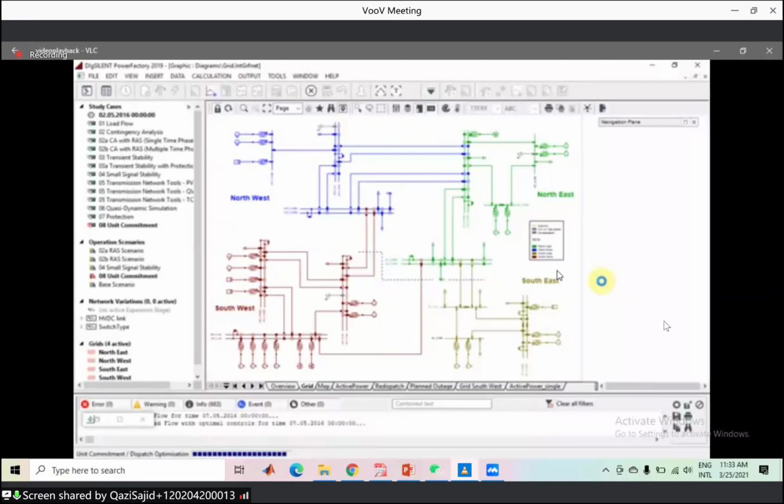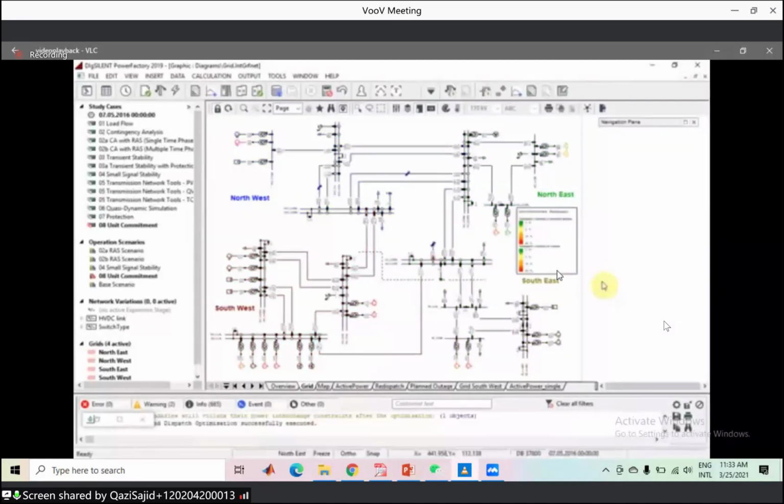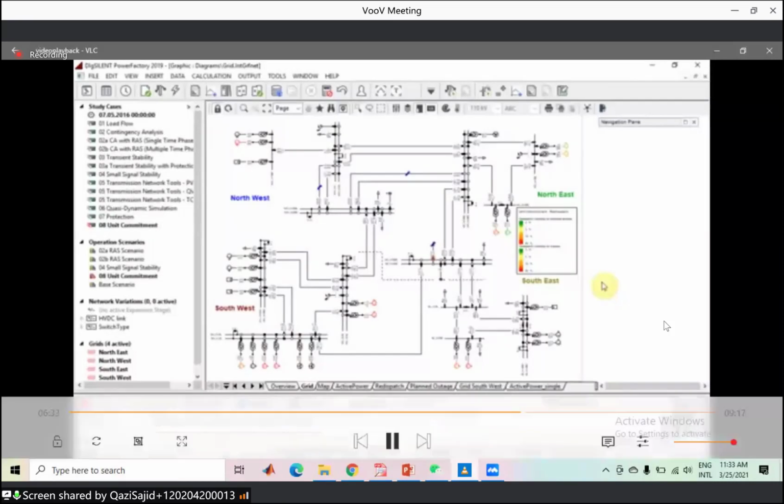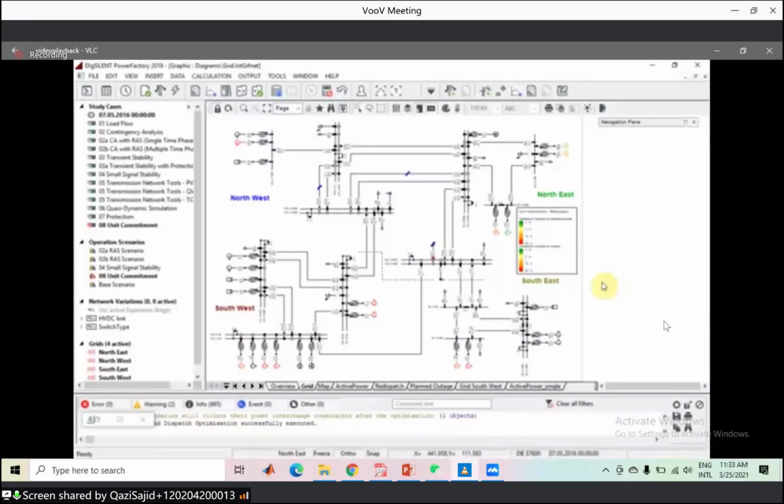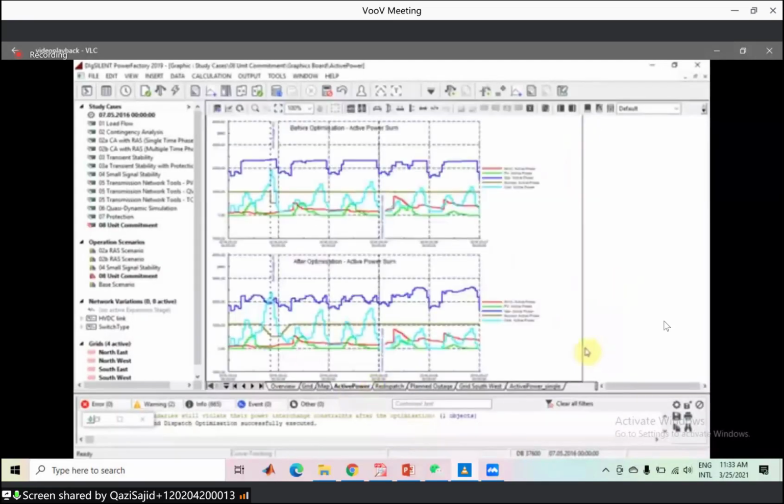there are several ways to view and investigate the results. Statistical results can be viewed in a flexible data page, or on a graphic, and result quantities across the time period are also available and can be visualized using plots. These plots show the active power dispatch summed up for the different fuel types. The two plots show the generation as it would be using a simple quasi-dynamic simulation, and then as it is after the redispatch by the unit commitment optimization.